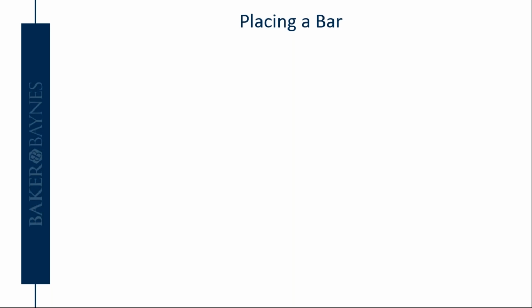So, placing rebar. The first thing I think to keep in mind after you've got your families loaded and after you have a valid structural host is that when you start to physically place the rebar, keep in mind that rebar can only be placed in section. So that means whatever view you're in, whether it's an elevation view or a plan view or a section view, it has to be physically cutting that concrete element to be able to make use of the rebar tools.